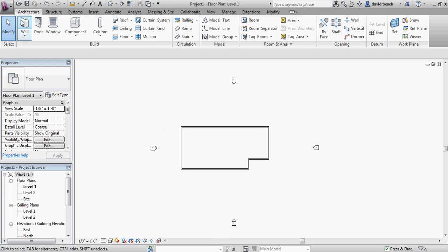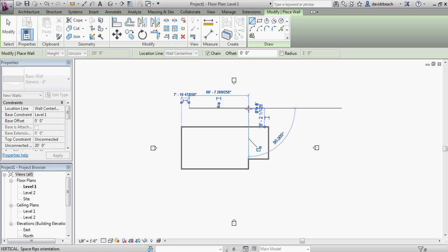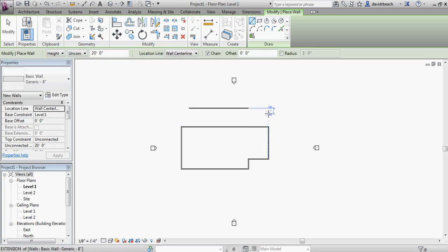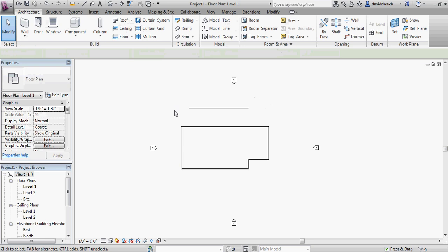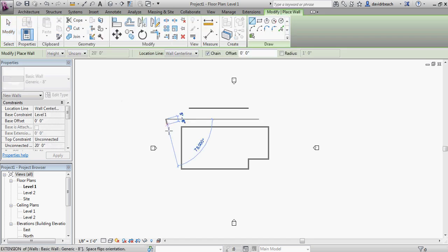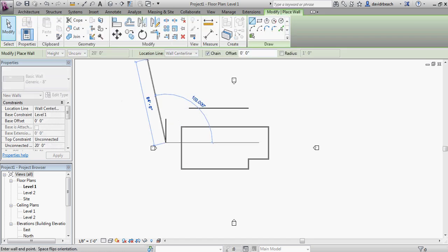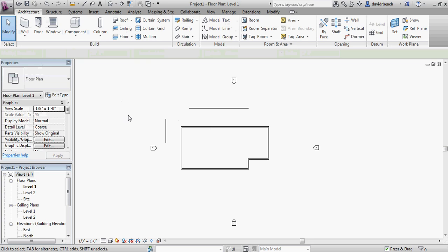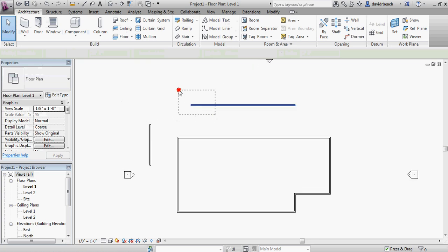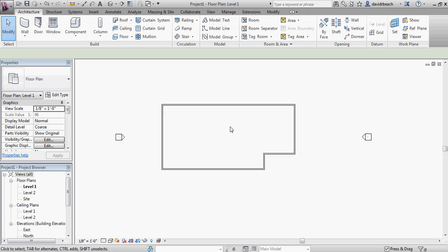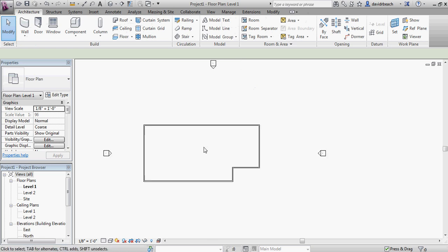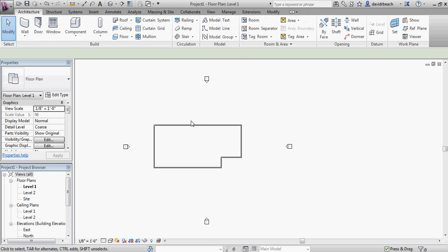So there's two ways to do that. If I'm in the menu and I'm drawing a wall, I can either choose to hit escape once, which still keeps the wall tool active, or I can hit escape twice, which drops the tool altogether, or I can tap or left click modify, and that does the same thing. For me, I typically use the double tap of escape. It becomes sort of second nature as you want to drop a tool to just tap escape twice.